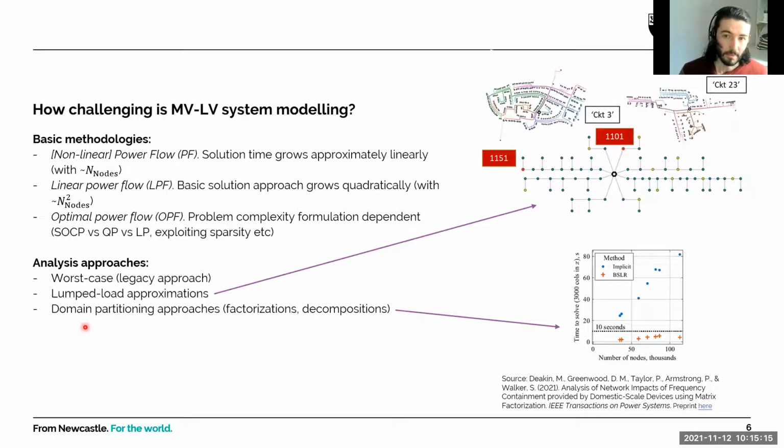Because the distribution network has this tree structure, there's a structure in the coupling between the voltages. In this paper that we got accepted in the summer, we implemented what we called a block sparse plus low rank formulation, which is a linear formulation, which we show in the paper is much more efficient than having this massive n squared nodes, which becomes infeasible at these big network sizes. So there are lots of interesting things for people to work on going forward.